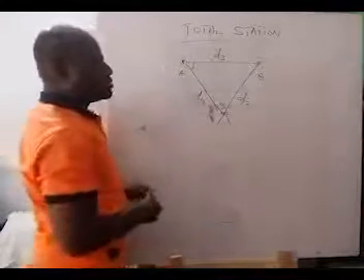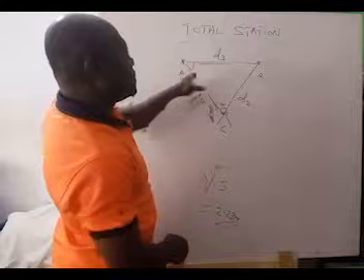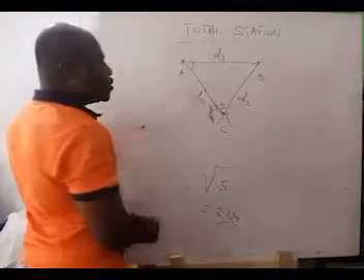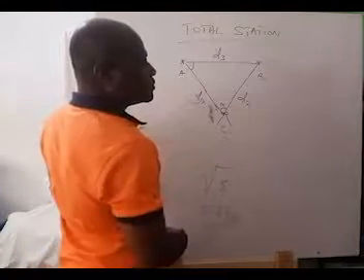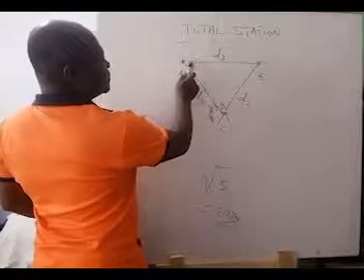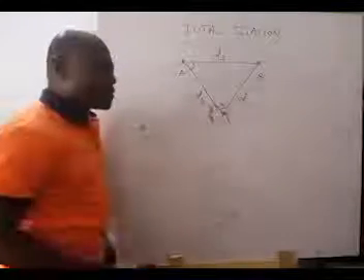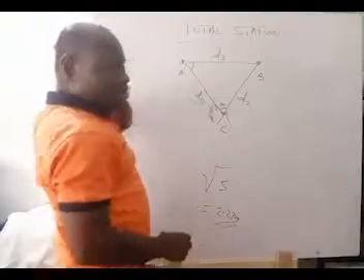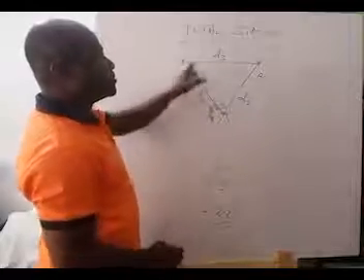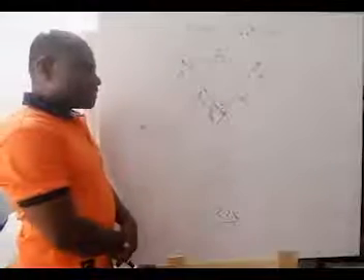It knows this bearing. So it gets this angle it needs. It adds this angle to this bearing, and it gets this bearing as well. It knows this distance, so it can calculate the coordinates of this. So it uses the cosine rule, sorry, not the sine rule, to calculate this angle. It gets this angle, it adds it, then it can get this coordinate. As soon as it gets the coordinate, it can now orient itself because it knows the coordinate, and it knows this bearing. So it can calculate any coordinates in the space. That's what it does.